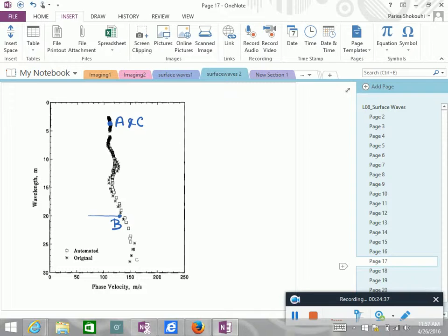Yes. Okay. To get a dispersion curve, typically it's not enough to have one set of receivers. The rule of thumb is that if you are probing like 15 meters, you need to have receivers that are 15 meters apart.